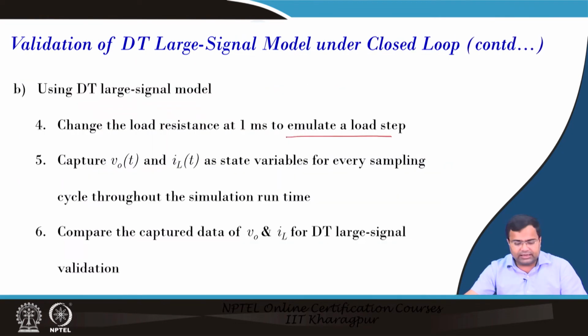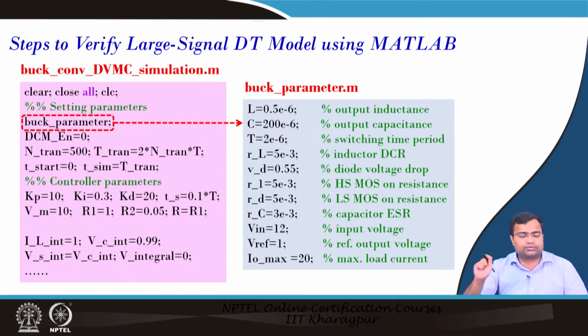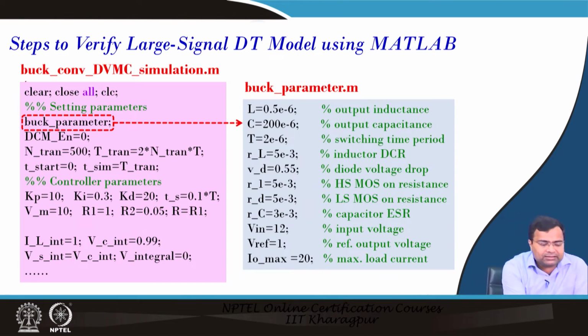That means the last step will be, we will compare the discrete time large signal model as well as the switch simulation result. So, let us go and check. This is the code that we are going to demonstrate in MATLAB. The first code, we are writing a digital voltage mode control in a buck converter, and that is a